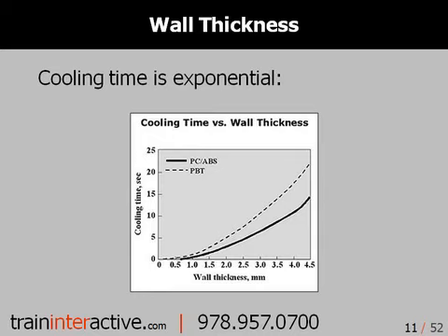In other words, you will note steep cooling characteristics on materials like PBT with a narrow range. Other examples of materials with a narrow melting range are nylon and acetal.